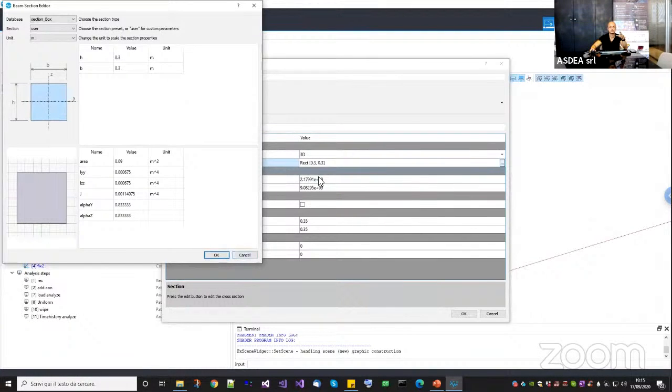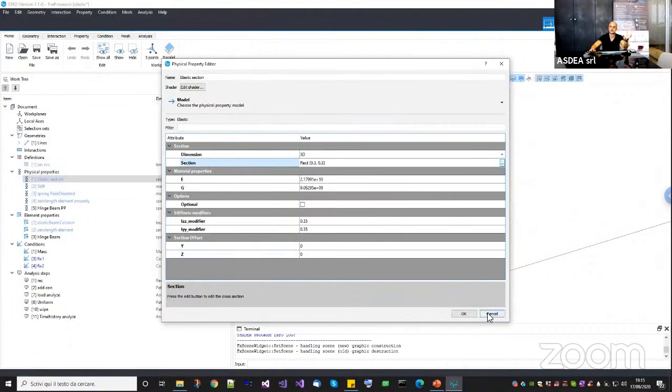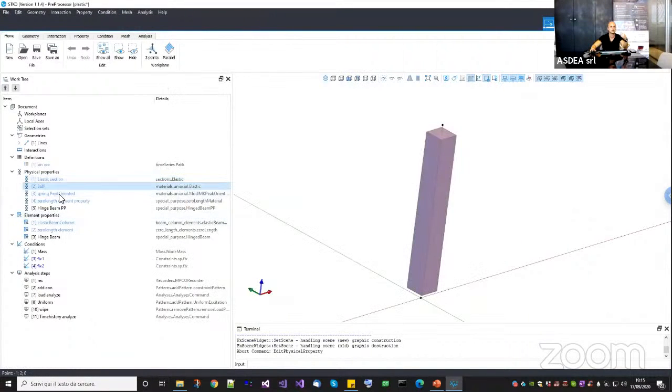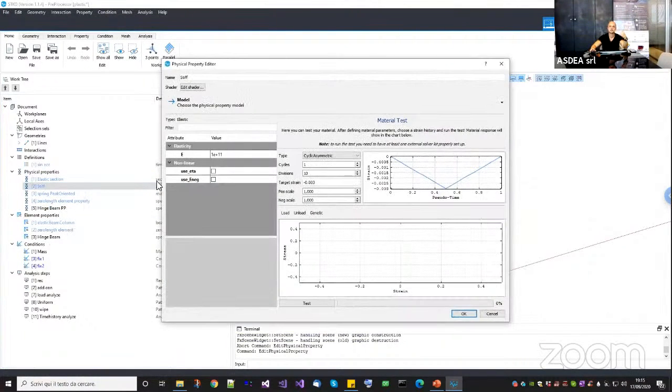So the bending stiffness will be something to the power of 6, okay? And then I add 3, 4 orders of magnitude. I don't want to make this number much stiffer, because otherwise my model will be ill-posed. But it should be stiff enough to impose a constraint. So let's say 2, 3, 4 orders of magnitude are fine. That's why I've chosen this one.